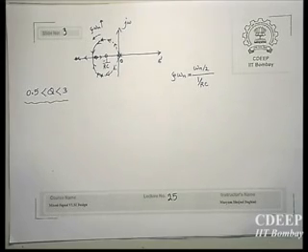See, zeta omega n eventually determines the time constant. And now here if you look, these poles are actually telling you what are the roots of that second order equation of which the time constant is determined. See, what is that zeta omega n? Zeta omega n is the real part of the pole. And that is the reason we say that zeta omega n determines the bandwidth and the speed eventually.